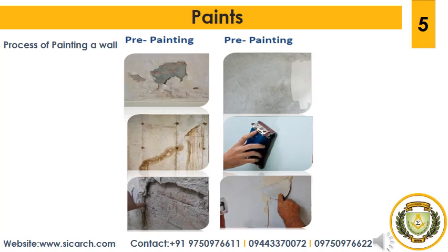A second pot is taken and it is covered with a canvas which is held tightly. The mixed paint is then allowed to pass through the canvas into the second pot. The brushes may be used for this purpose. The paint is then ready to use. The mixed paint may be prevented from drying by maintaining a thin film of linseed oil or of water at the top.